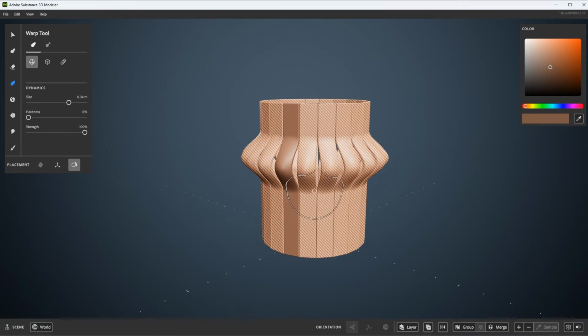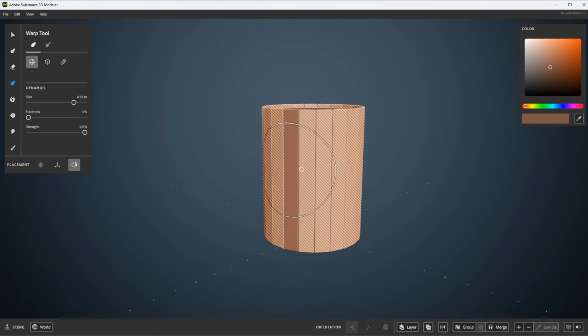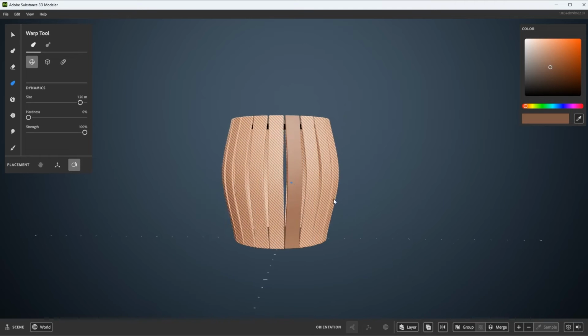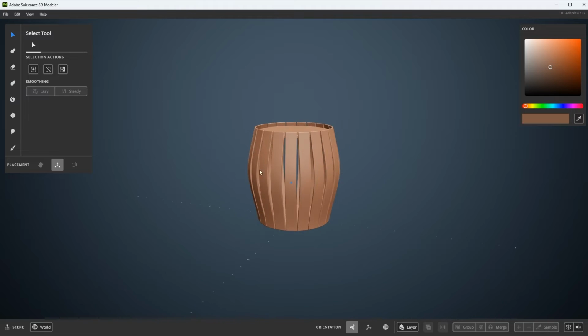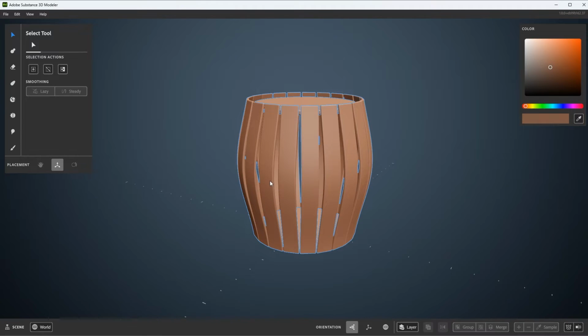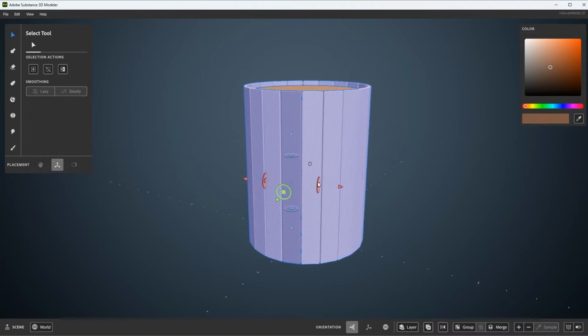planks. Looks pretty good. So what I could do, let's scale this guy all the way up. Let's hold down the Z key, left click and drag, and there we get that nice kind of bend that I was wanting. So that's an option. We could go in and do that. However, there's another way of working with this tool. So let me just Control Z to undo that.